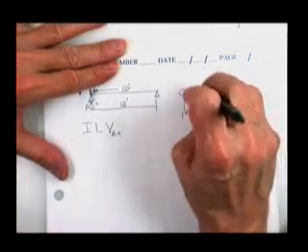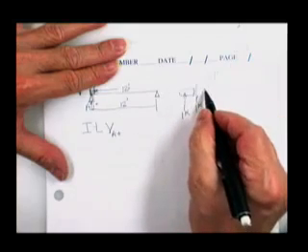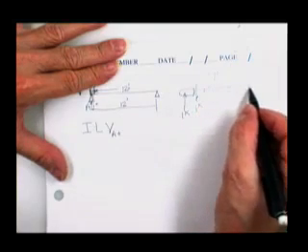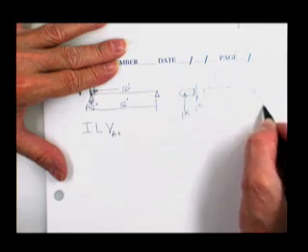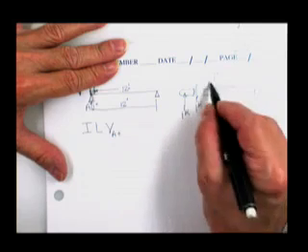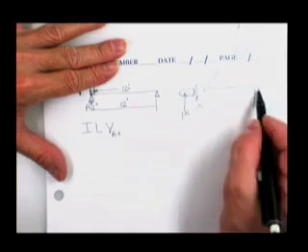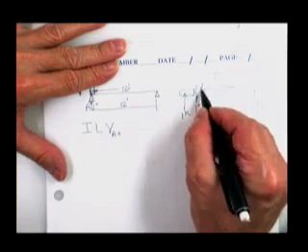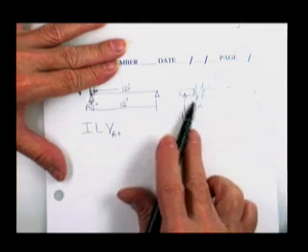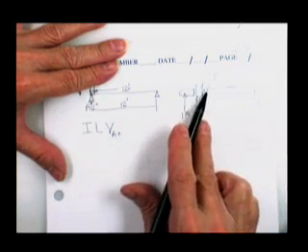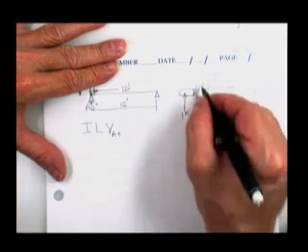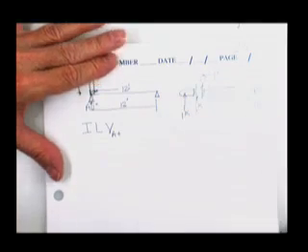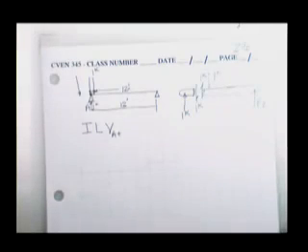Now then, if you did do the other end, here's what you'd see. You'd see the beam. You'd see the reaction at B. You'd see he has a 12-foot moment arm. You'd see this guy has a 12-foot moment arm. You'd see the shear going up instead of down. And 1 times 12 is balanced by somebody times 12, and therefore there'd be a 1 kip there. So you can draw either side, and you still get the same result.